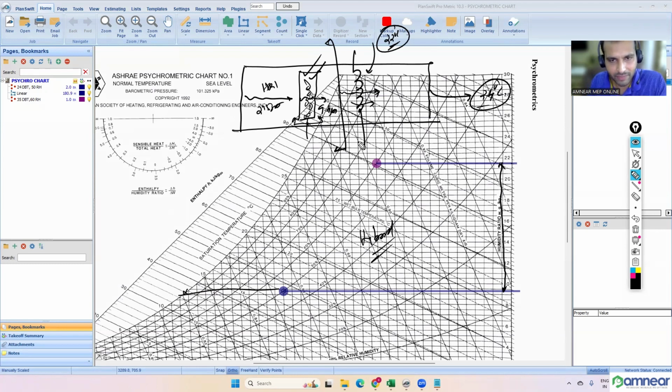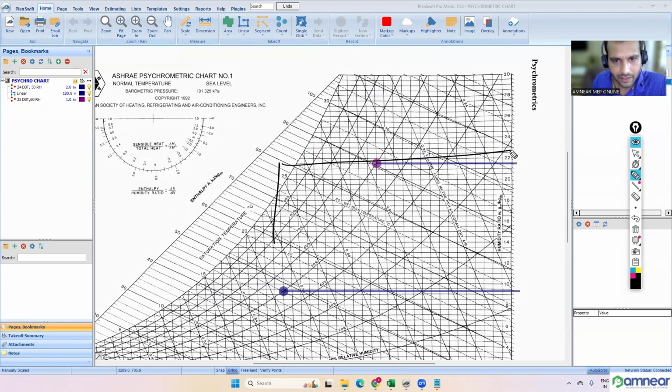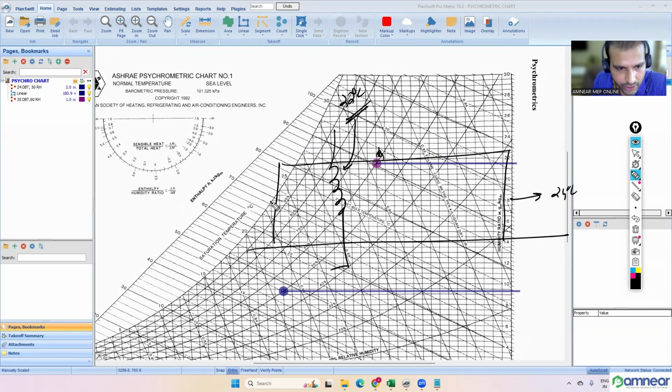And this is not exactly the hybrid system. Hybrid system, for example, initially we will be having a cooling coil. For example, if the supply temperature that we require is 24 degrees Celsius, as per the site condition, we might be keeping the surface temperature of the cooling coil at 22 degrees Celsius. Anyhow, if you want to cool the air to humidity ratio 2, then you have to cool it up to 13 degrees Celsius, correct? If you need to achieve humidity ratio 2, we have to cool it until 13 degrees Celsius.